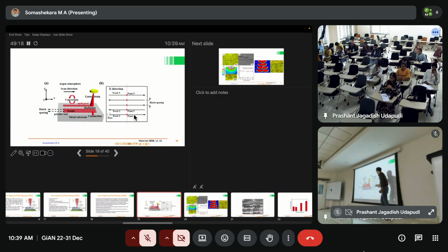Say, for example, you start here, you go like this, and then like this, and then come inside, going to the interior, which is like a counter spiral in, right? So when you go like this inside, you are generating more heat. It is concentrating at the middle of the plate, which at some point will overheat.